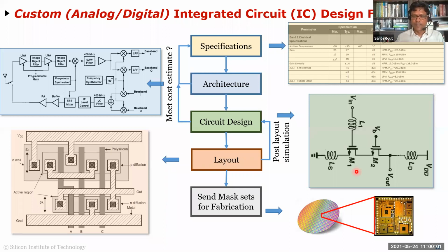Why don't you capture it in here? Like I said, you just don't know till you lay it out, right? You have a model for this transistor which will tell you in isolation what the model is, and that's what you're simulating. You have IV characteristics of this: the drain current versus gate, drain current versus drain to source and so on, assuming this is in isolation and there's nothing connected, there is nothing beside it and so on.